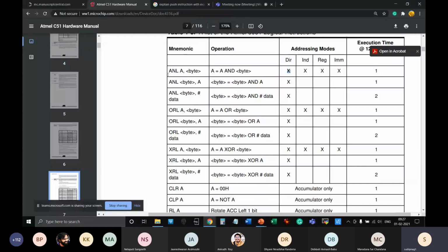So this is an 8-bit address I'm giving. Now, whenever I give an 8-bit address, it doesn't straightaway go to the external RAM or ROM. It doesn't go outside the chip. It will only stay within the chip. So that means this 8-bit address must be somewhere within the internal RAM.